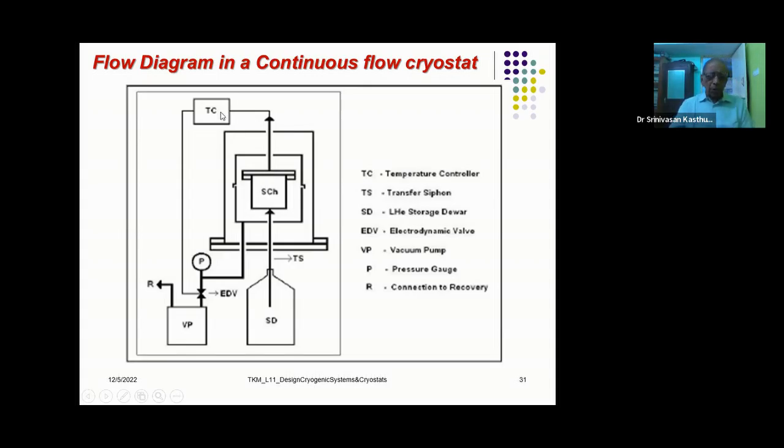And the electrodynamic valve controls what should be the sample temperature. So a temperature control is automatically incorporated. It allows or adjusts the quantity of the cryogenic fluid that is taken out, that is pumped into this whole chamber.